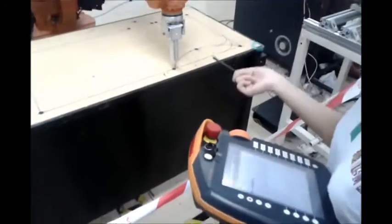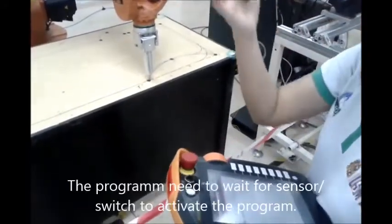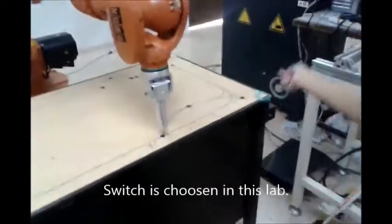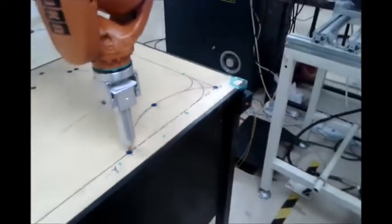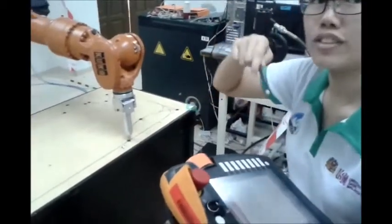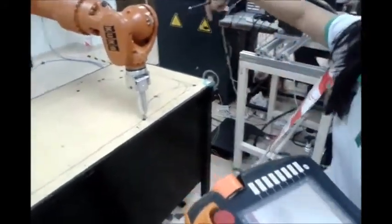So after the wait command, now I would like to add the wait for command at this point. So when the KUKA robot moves from this point to this point, it needs to wait for switch or sensor. But in today's lab, we are going to choose switch. So when the KUKA robot reaches this point, the light at the EPC board 11 will turn on, and when we switch it off, then the light will turn off also. Then the program will be continued.